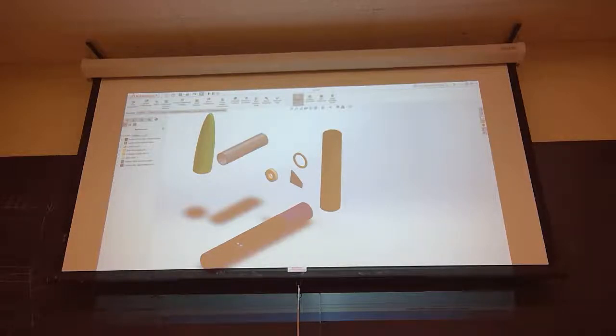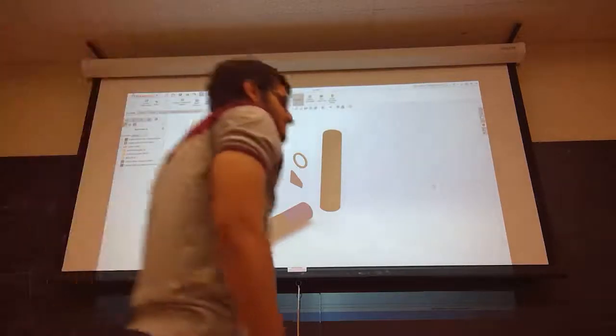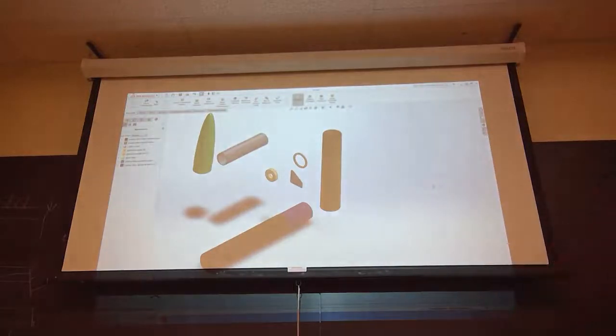So this is a coupler tube. We're gonna connect the black tube with no slits to the other color tube with slits, okay? So we want the coupler to be half in our tube, or in the black tube currently, and then half in the other tube, okay? So the coupler tube is 12 inches long. So we want 6 inches of it in the black tube, okay? So we're gonna do that using a distance mate.